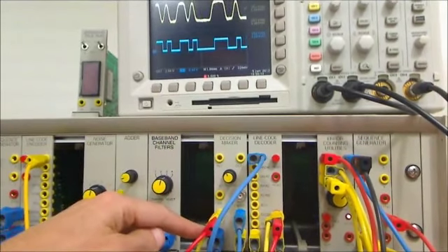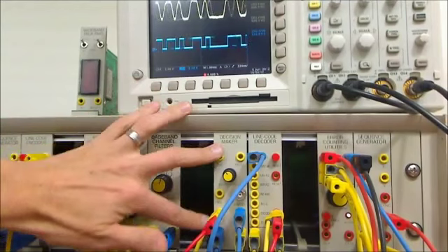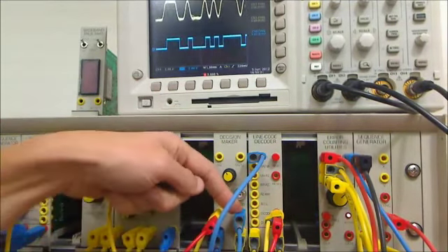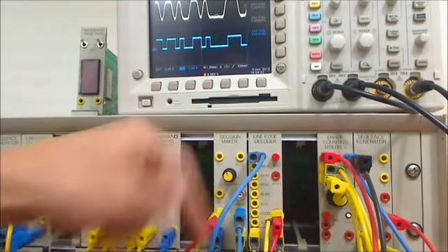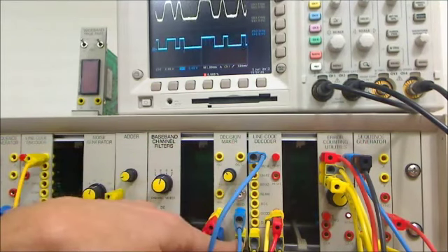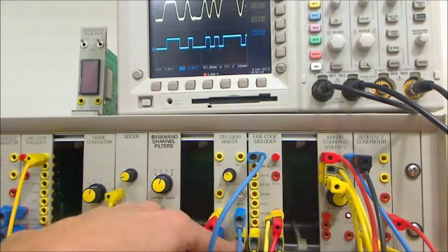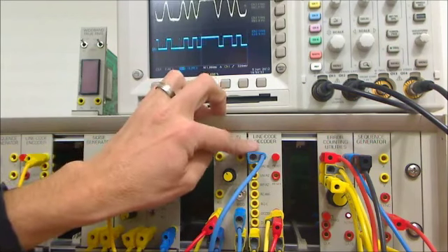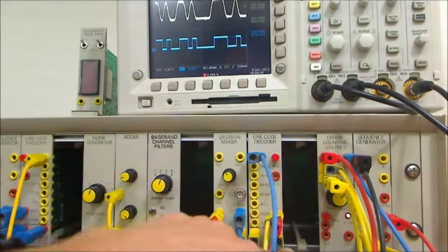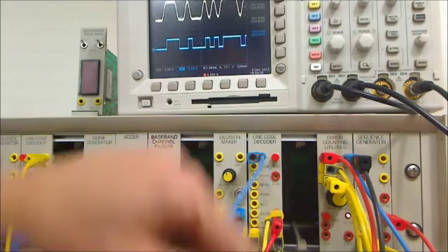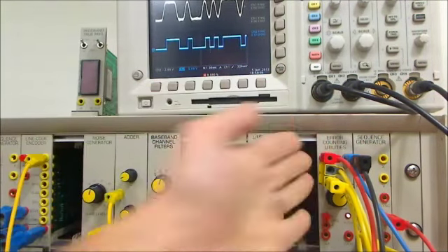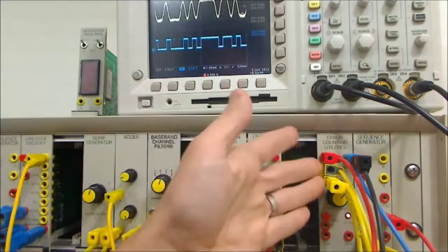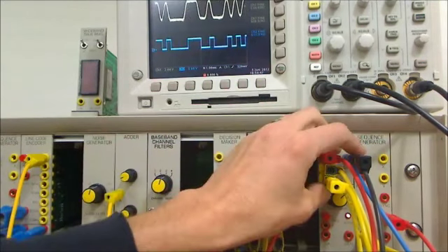Just taking a step back, look at these clocks. The decision maker makes a decision, and as well as outputting the sampled signal, it outputs an appropriately phased bit clock. This clock is fed to the line code decoder, which also outputs its own phase clock, which is then passed to the error counting utilities. So now we're operating with a local clock which is aligned to the data.